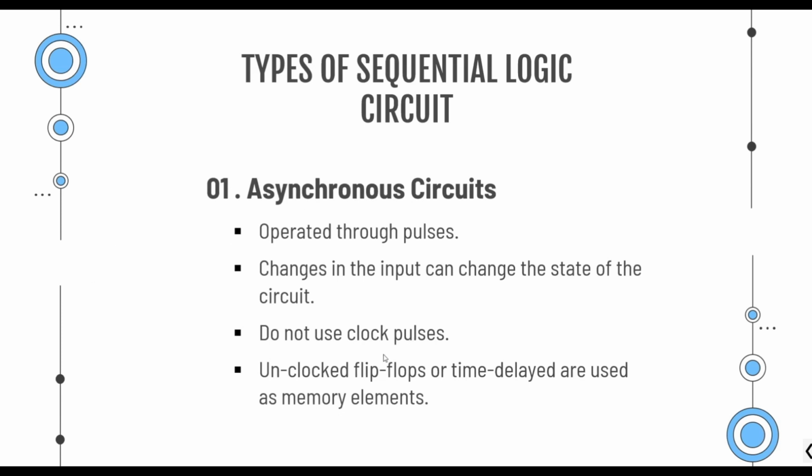However, this asynchronous logic is more difficult to design, and it has problems not encountered in synchronous designs. The main problem is that digital memory elements are sensitive to the order that their input signals arrive. If two signals arrive at a flip-flop at almost the same time, the state that the circuit goes into can depend on which signal gets to the gate first. Therefore, the circuit can go into a wrong state instead of the expected state.